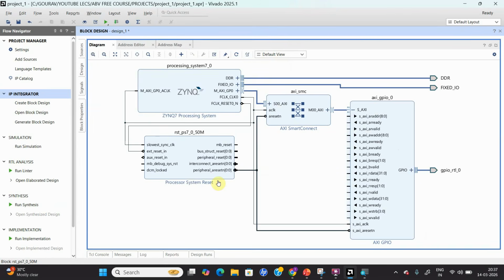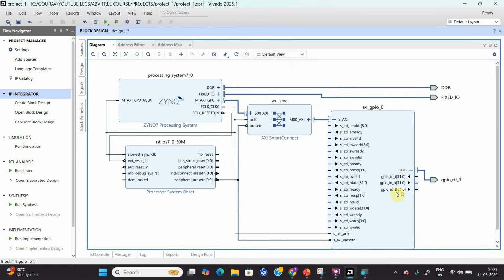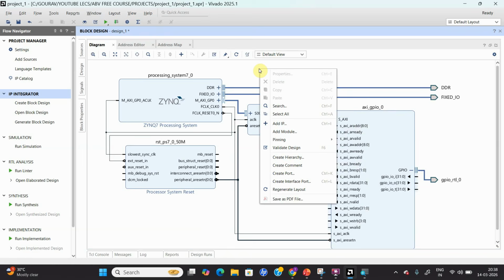So this is how your GPIO is going to look, where we have our processor, and this is my interconnect, which connects your master and your slave, which is nothing but your GPIO. Internally, this AXI interface will be connected to an APB interface and converted into GPIO related signals. See, here we have our GPIO related signals. So instead of using APB based GPIO, we have the option of directly using AXI GPIO, where internally there is some code which converts these AXI signals into GPIO signals. Is it clear, guys?